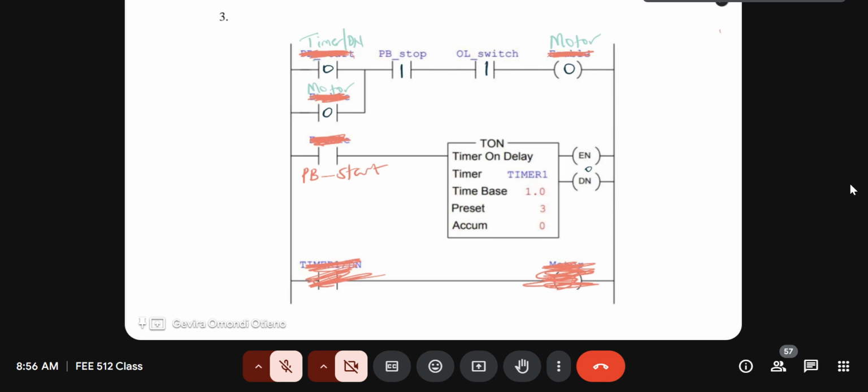Okay? Now, let's come to rung 2. Rung 2, before you press the push button, it's at logic 0. But now, let's see what happens if you press, because notice it's 0, so the motor is not running in this case. It's not running. But now let's see, if I press the button, so there's a start button there. Okay? So if you engage the start button here, then now I close the contact. So I get a logic 1 here.